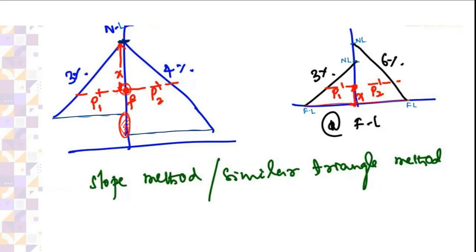Sometimes the full load points are given as the same and the no load points are different. They won't give you the graph, they'll mention only regulation constants from no load to full load. So please be careful. If the generators are operating at full load points and at rated values, then take the full load points as equal, and then proceed. Again, I'm saying do not select the common operating point in this zone. It's a non-operating zone.